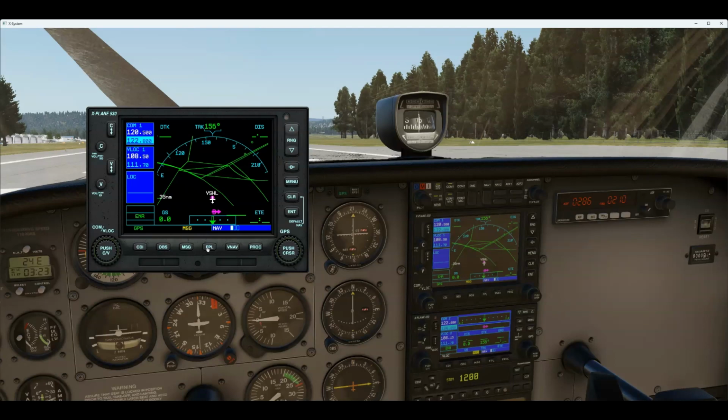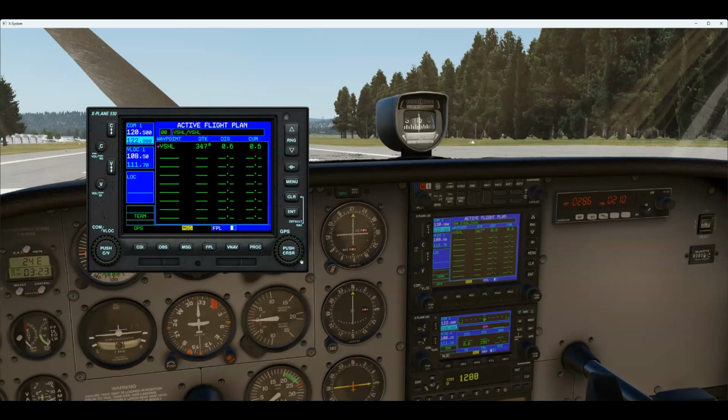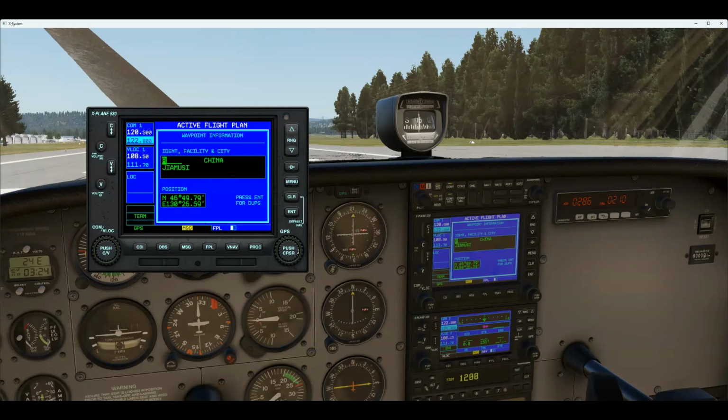When you're going to input a flight plan, you press the flight plan button. It's in its outer mode. You press the button here to get a cursor showing. You'll scroll with the outer wheel, and the inner one is for inputting stuff. So if we want to get to Nowra, we manually go with the inner wheel to Y, outer wheel, move along one, inner wheel, go to S, outer wheel, move along one, now we'll go to N, outer wheel, move along one, and now we'll find the W. I'm just using the mouse wheel, so it's not too complicated.